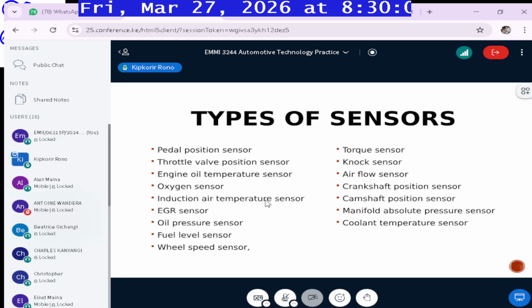So in that case, sometimes you find that it's also not efficient or effective in transporting the heat that is developed in the very internal parts of the engine where the coolant cannot reach. So you find that the temperature of the oil can rise for that reason. So it gets heated up instead. It even reaches a point where it boils. So it's usually a pointer of the need to change the oil.